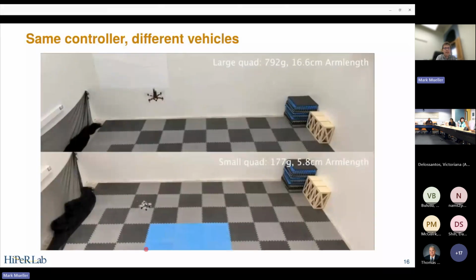And what you're seeing here is these two vehicles doing a very boring flying back and forth, but with the controller here having no access to any special data. So the controller here only knows the IMU data and the commands that we're sending the vehicle, and it is figuring out what commands to send to track this back and forth trajectory that we're flying. So that's good. We can do more interesting things.